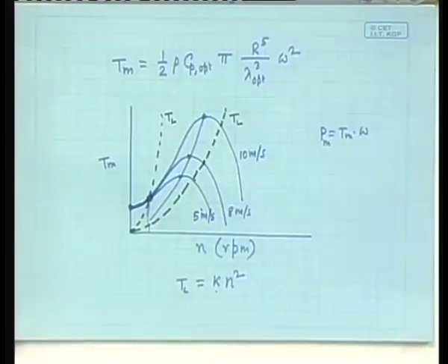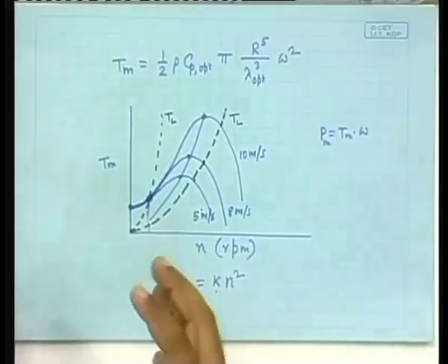So, you see, it is not only the pitch angle that needs to be controlled, it is also the characteristic of the generator that needs to be controlled, and the torque ultimately depends on that. If you can control the power that goes out from the generator to the load, then there is a speed of rotation.